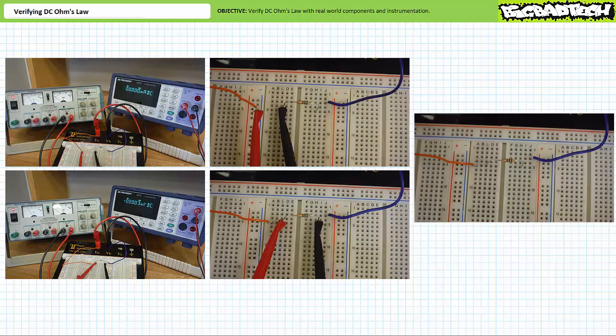No current is a clear sign that there is an open somewhere in this circuit. You know, the circuit has the positive terminal of the source landed at node 5A through E. One terminal of the nominal 560 ohm resistor also landed at node 5A through E. The other terminal of the resistor landed at node 5F through J across the ditch. However, the negative terminal of the source is landed at node 3F through J. No connection exists between node 5F through J and node 3F through J above it, and no path for current exists.